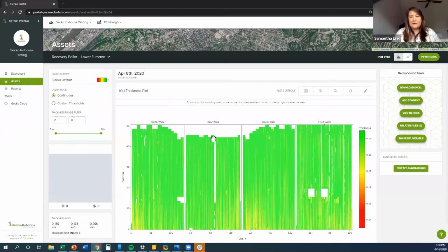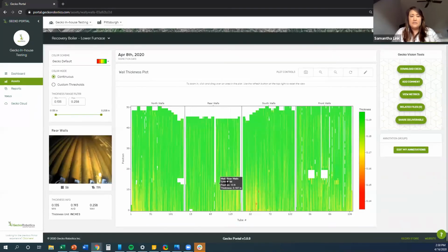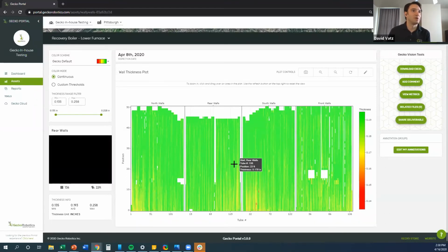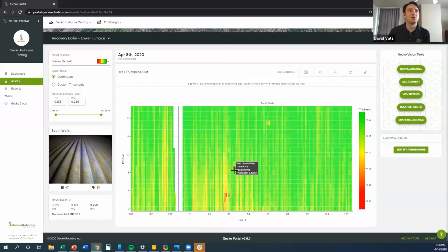So everyone kind of heard the 12 million data points. Do people normally have access to all of the UT data that's collected? Yeah, it's a good question. So I'll show you on this one right here. What we're doing is taking those 12 million data points, and for each one linear foot on a tube, we're picking out the low reading for that one foot section.